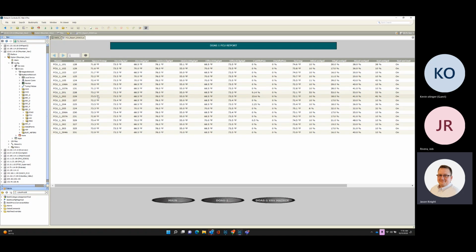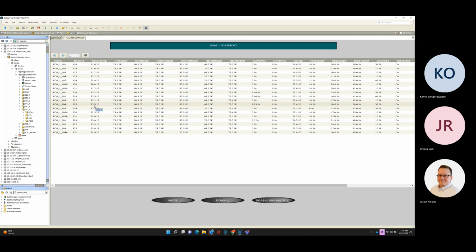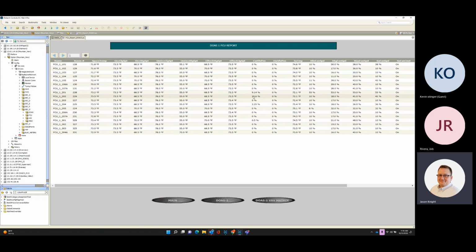But you can see it's 8 o'clock in the morning, 8:18, and we got a couple rooms that are already starting to warm up. They're right at set point. Chill water valves starting to crack open. Some of the rooms that are on the southwest side, I've made the algorithms a little more aggressive, so the valves open a little bit faster. Obviously, because when it's sunny out, you got 3 stories of glass and brick, and it heats up very fast.